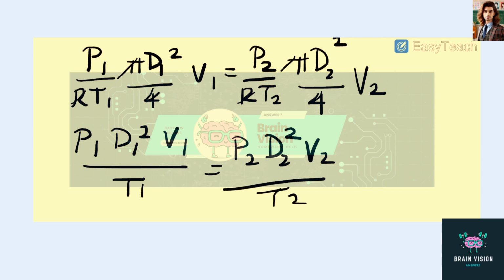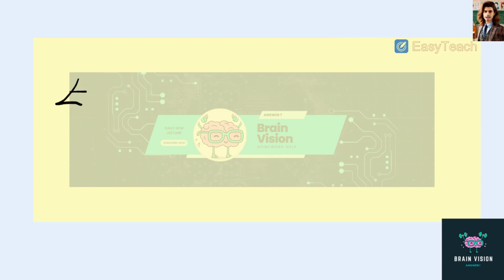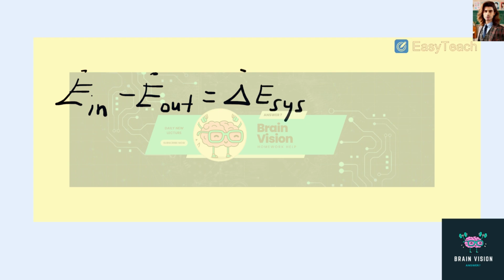Next, what we're going to do is our energy balance. Similar to our mass balance, we can say that the rate at which energy enters the system minus the rate at which it leaves the system is equal to the total change in energy rate of the system. As we assumed before, this is a steady state process, so this is going to be equal to 0. Therefore, E dot in is equal to E dot out.